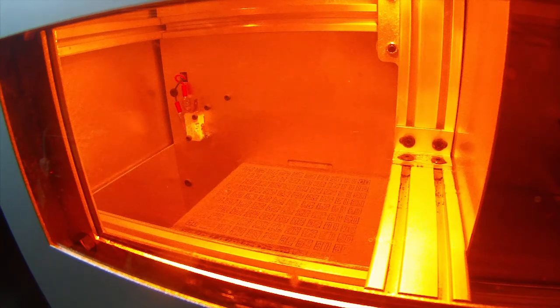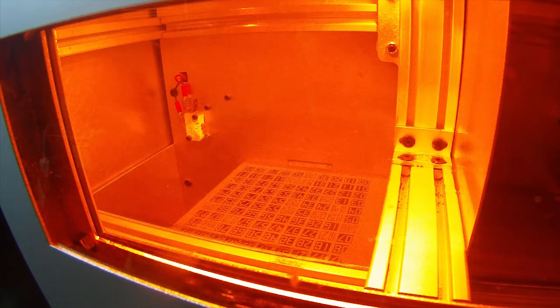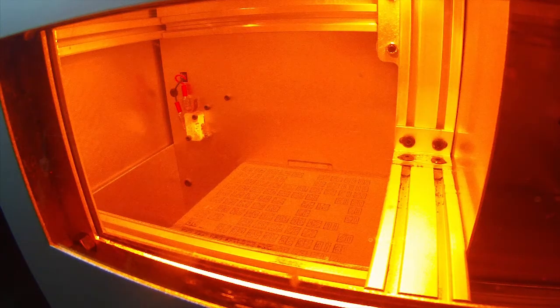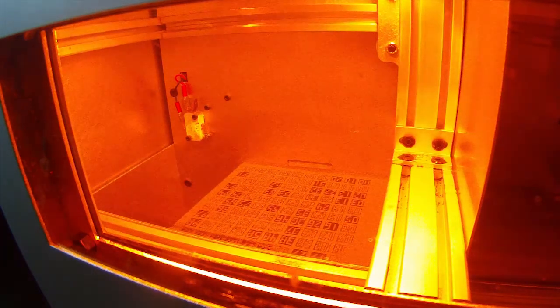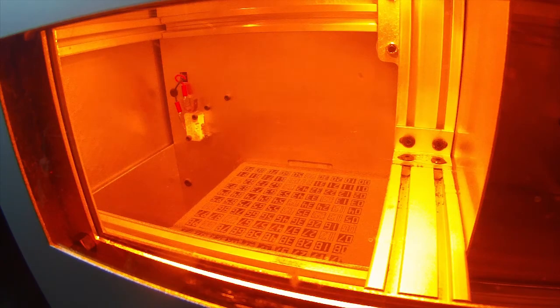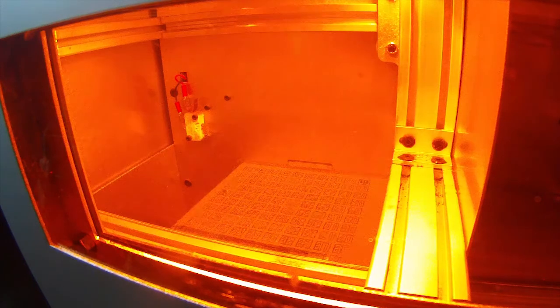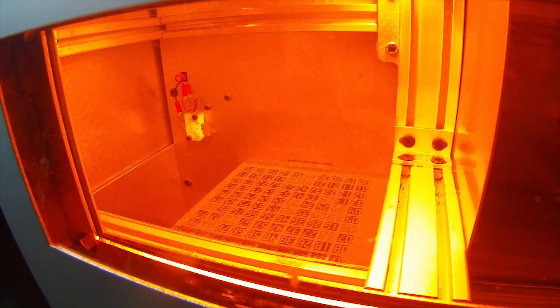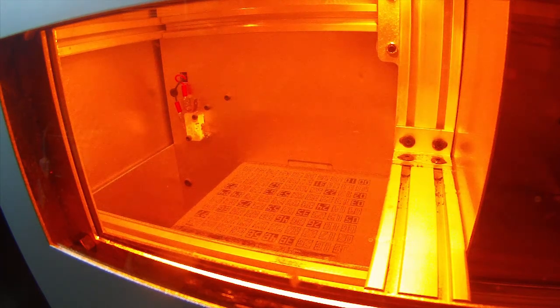You can see right there, the plow just happened on the bottom of the front of the bed, and it still keeps sintering if you keep going. So I adjusted the calibration. Now it's at 172.7 degrees with a 550 laser speed. I still had curling issues on the front right side, which is basically elements 9, 8, 18, and 19. Also had curling around 92 through 98, which is the full left side.